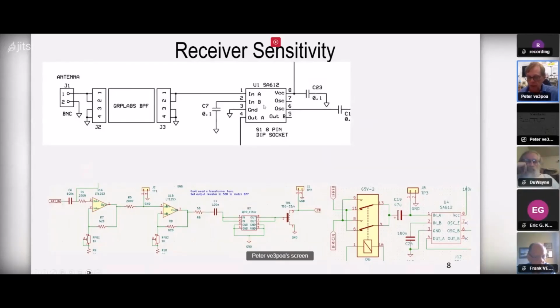Which means in the case of the Phoenix, we've utilized matching transformers, and in the case of the DCR, there is none. The receiver bandwidth we took care of with a crystal filter designed around the single sideband signal. Now, having said all this is not to criticize the DCR. It works very well. The Phoenix receiver is just an evolution of the DCR.